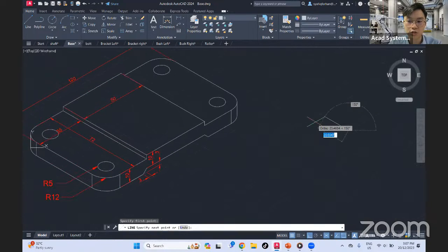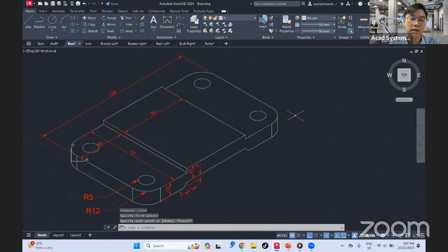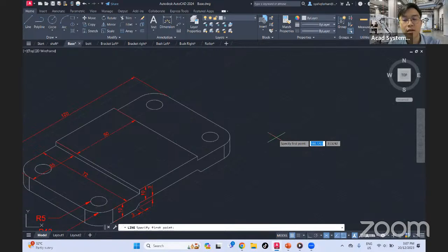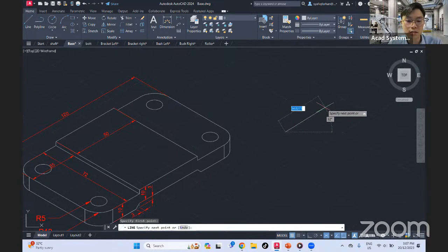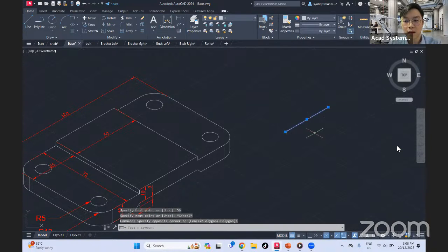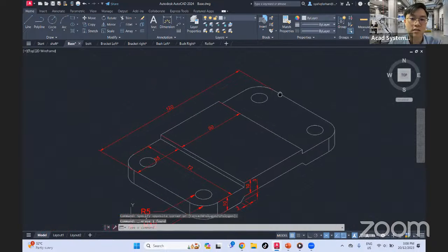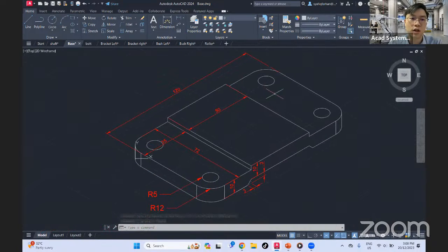So this isometric drafting mode just makes our life easier. Usually, if we want to draw an isometric drawing, the conventional way, the old way of people drawing by hand, is they have to use the triangle ruler to measure the 30-degree angle. Or if you use AutoCAD without this function, then you probably have to enter the distance and then input the degree. So it is basically a life-saver, simplifying everything down to just how you would usually draw.